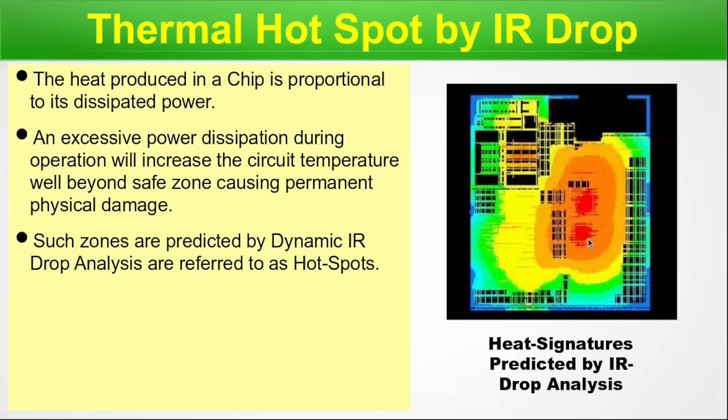Obviously the tool will give you the legends about the power ratings and dissipations happening for each color. So this is the heat signature. These are called the thermal hotspots, where different spots inside the chip can get heated, and if over time they are not cured, they will cause permanent damage. That is the purpose of the IR-Drop analysis, to detect these hotspots and correct them way before the sign off.